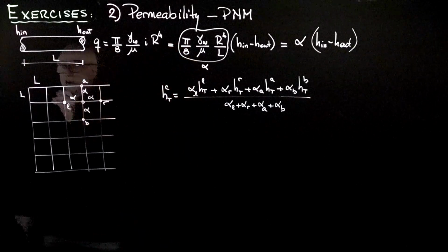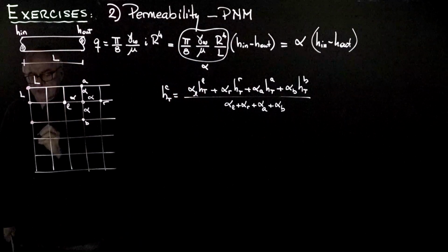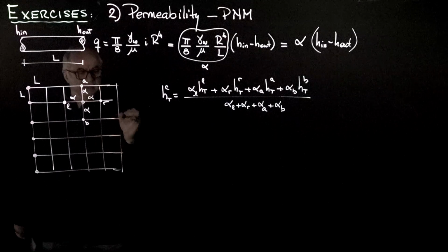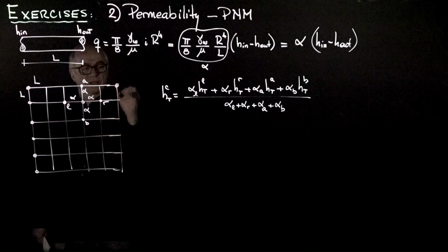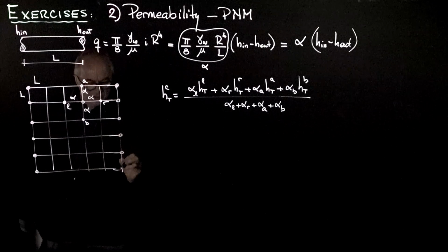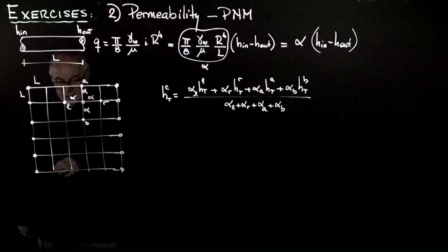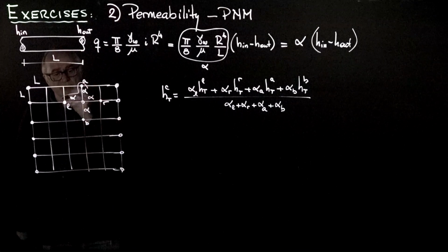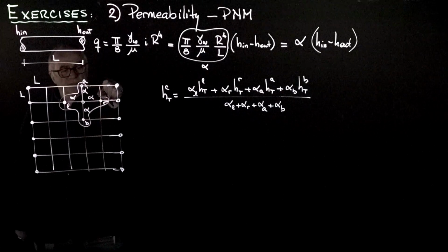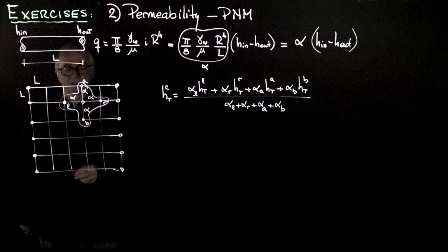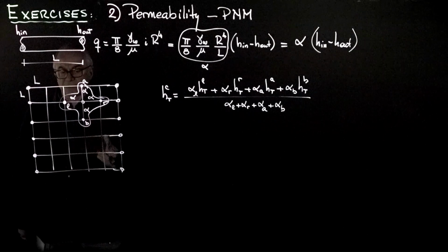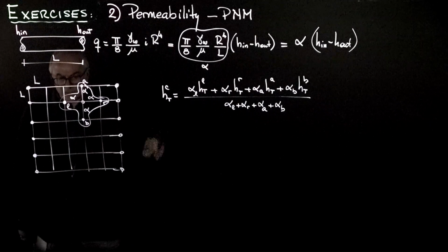So now we know the total head. We assign the total heads at the entry point, so those values are known. And in this case, I'm simplifying it. I think that in the homework it is 10 by 10. We know the total heads at the exit points, so there is nothing to compute. And we can place that kernel at any point, like we did here, this point. And you can compute the new updated value for the value at the center. And you keep moving the kernel around until the values don't change anymore, and that means that the system has reached equilibrium or the asymptotic condition.